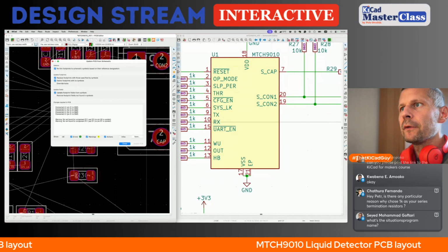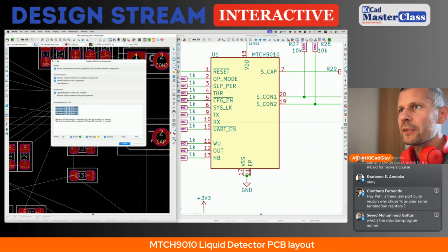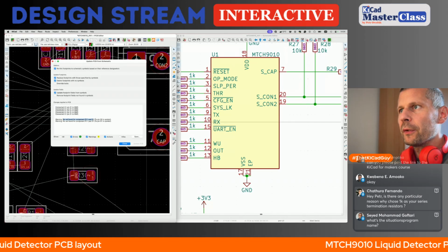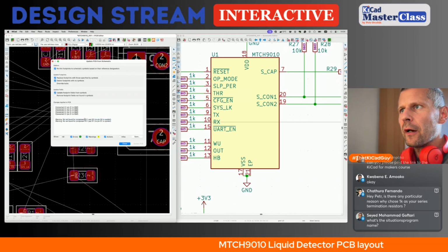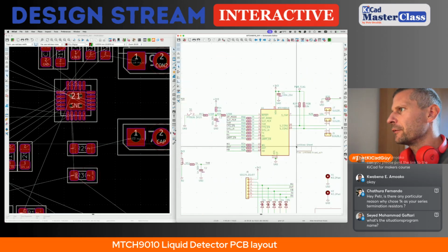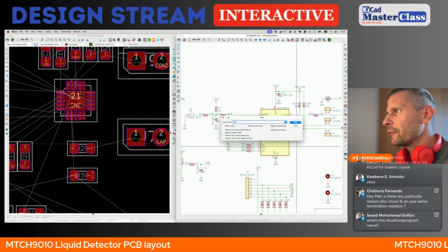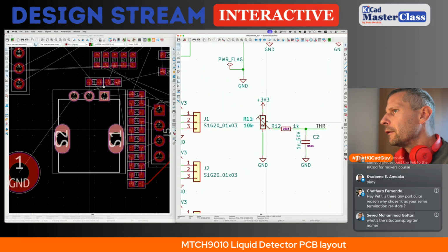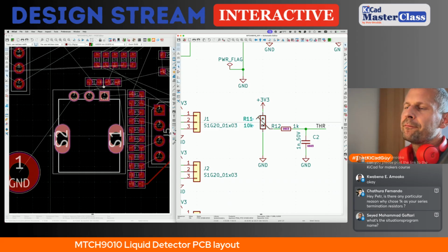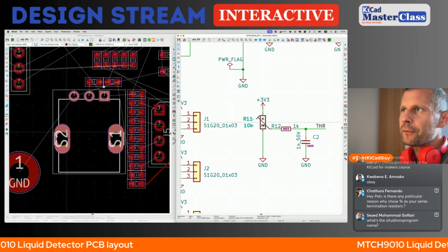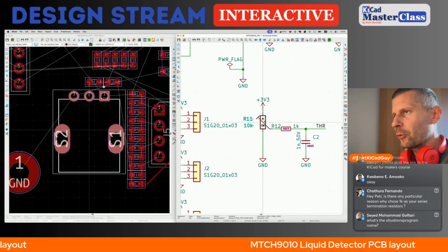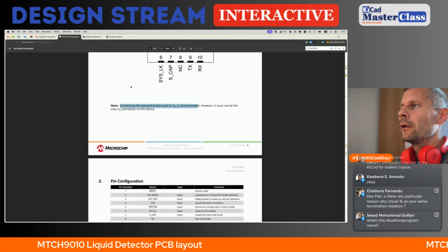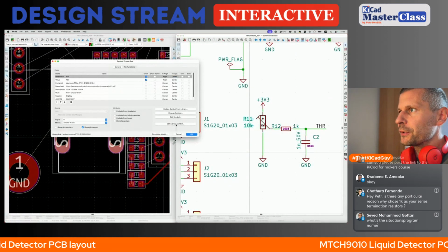So now pin 21 is connected to ground. And warning, no net found to component R11 on pad S2, no pin S2 in the symbol. R11, where is R11? R11 is here. Oh, I can see. Our footprint contains 2 mounting holes without the direct connection. So yeah, we have to add two ports to the symbol as well.